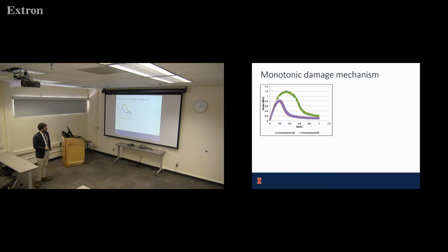So when we did that one, this stress strain curve actually just comes out something like this, and then it abruptly ends. So you see basically a ductile response, increasing strain, and then you just see the strain continue and continue, and then it just abruptly fails, and that's the end of the test. The material is separating.